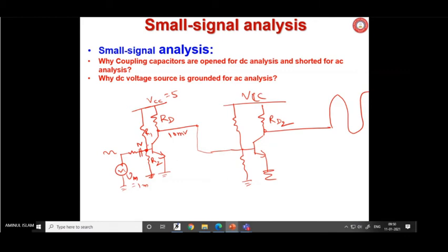But if you connect here, you see that it is amplified and some voltage is here. I mean, some voltage dropped here and some is available here, and that is going to be connected here. So the bias voltage, which should be 1 volt, is getting disturbed by this connection. So you cannot connect directly like this.